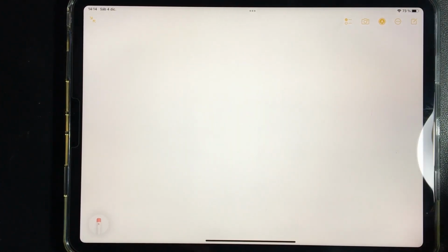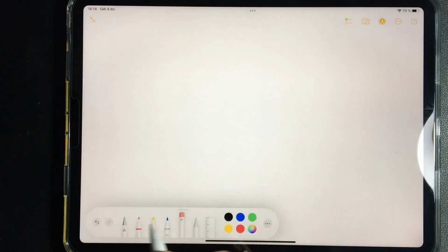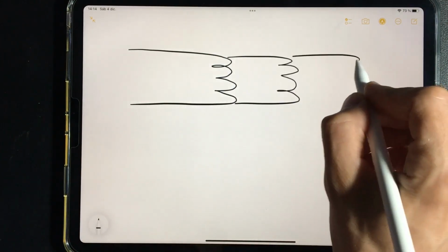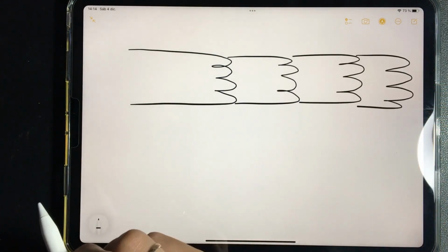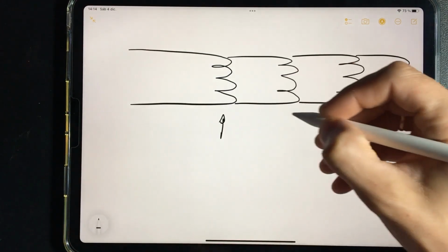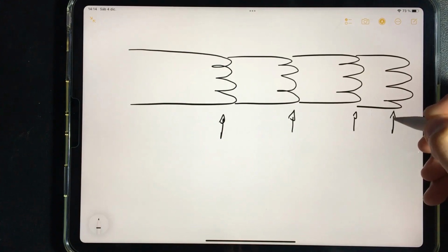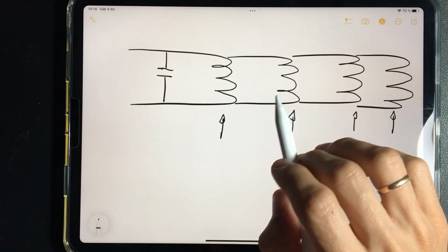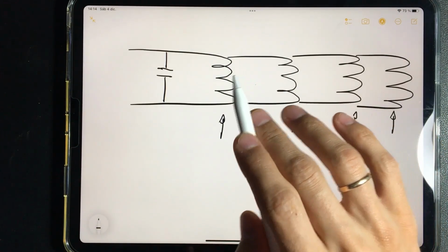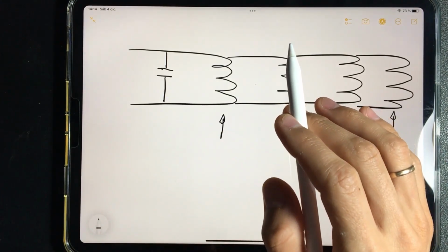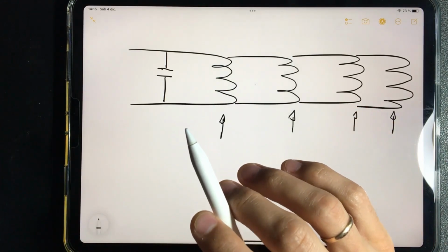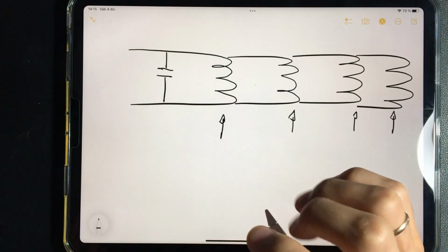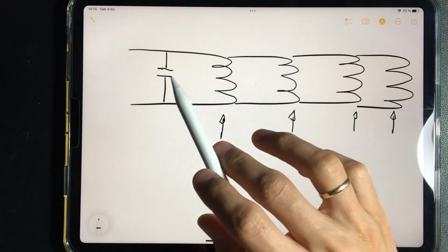For example, when in a factory we have many motors, these are the windings of the motors that I want to draw here. What is done is to place a capacitor bank to compensate for power factor. Why? Because coils and capacitors alter electron flow, and this has something to do with the low-pass filter circuit or double-pi filter circuit that we had been analyzing in previous modules. It has a lot to do because coils and capacitors function exactly opposite.